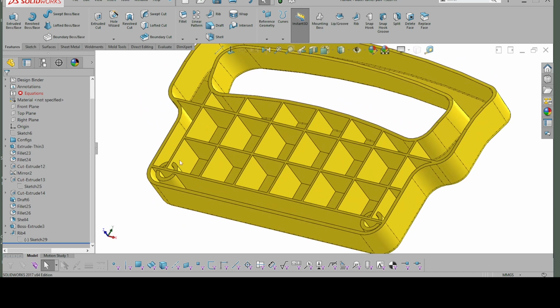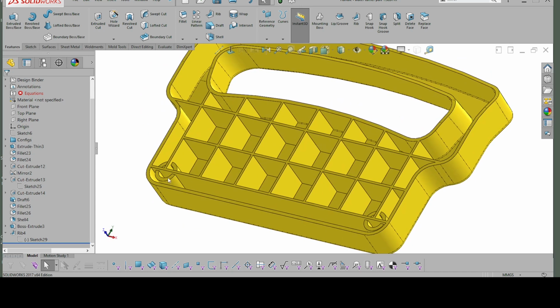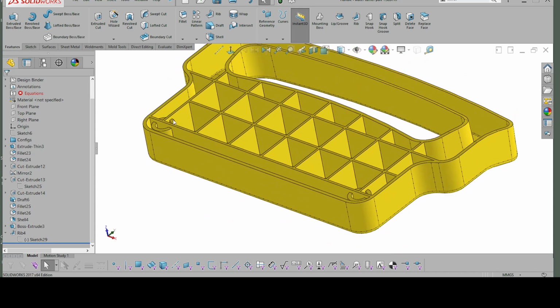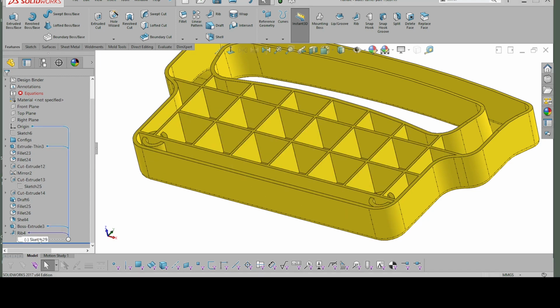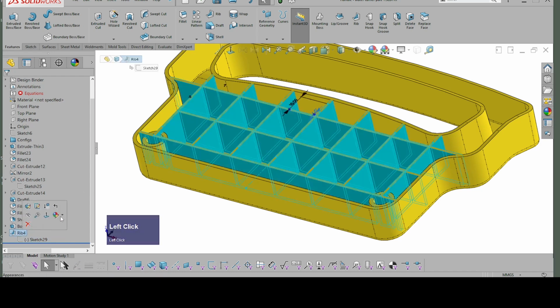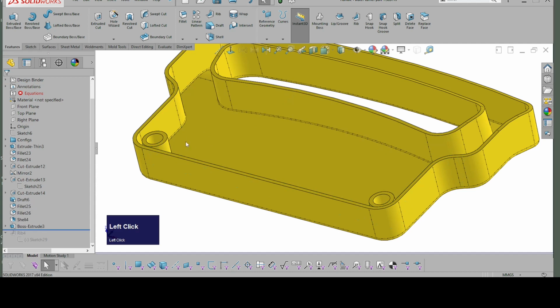One is that it's extending beyond the actual boss, and the second is that it's taller than the boss. So let's fix the taller than boss one first. And the way I do that, I've shown you already. I can go to the sketch, and if I click on it, I can say I want to edit the sketch plane. At the moment, I don't really have a good basis to do that because I've got nothing in a suitable region to put it onto. So I'm going to roll this feature back so it's no longer available.